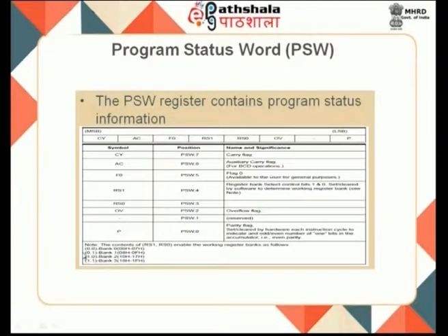What are all the addresses through which we will be using those particular registers will be decided by this RS0 and RS1. This is a combination. So, I can make 2 bits, 00 to 11. Rather you can look at over here, 00 will be the bank 0, the address for your R0 to R7 is 00 to 07, whereas 11 means bank 3 where 18H to 1FH.